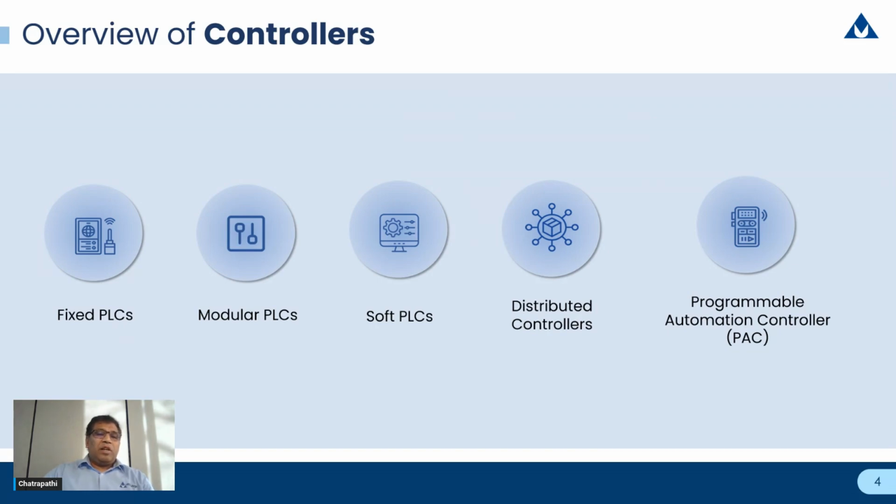And then the soft PLCs are basically PLC programs implemented in software and running on a PC or some general purpose computer. The reliability depends on the specific hardware on which they are running, since it's a general purpose PC. These are useful for less time critical and less data demanding applications.